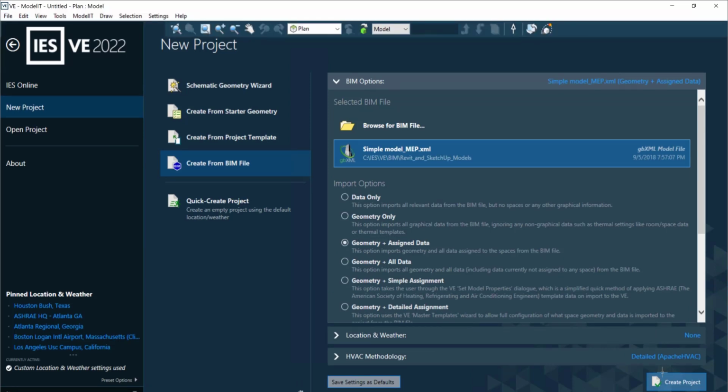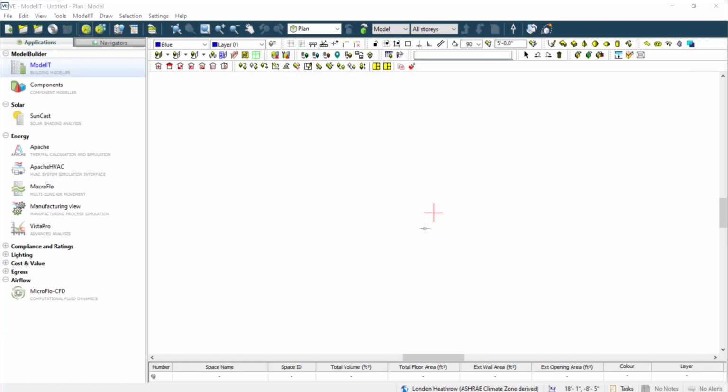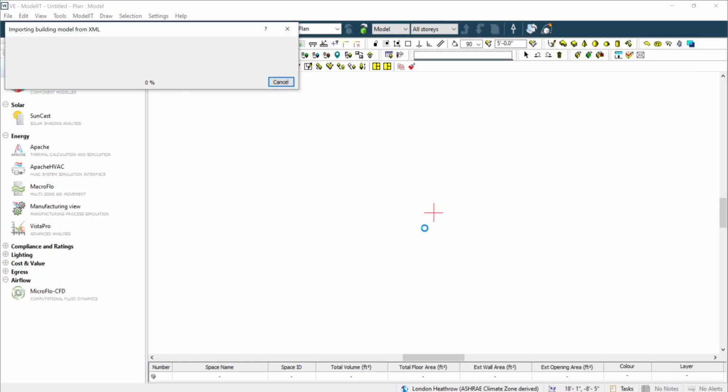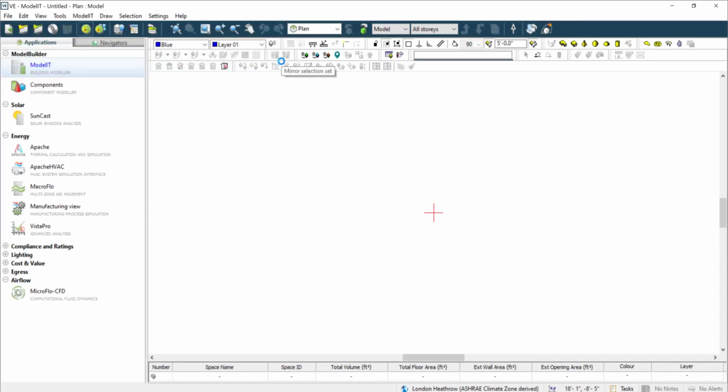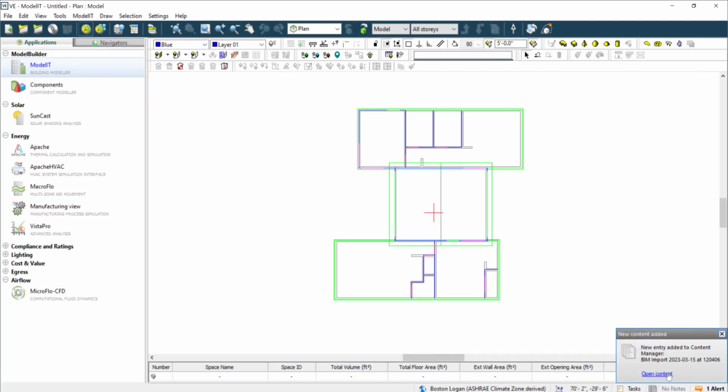It will also bring all of your internal gains, so lights, people, equipment, plug loads, associated profiles too. It will bring heating and cooling set points. You get this little report, by the way. You just click on the report. I'll come back to it in a second.